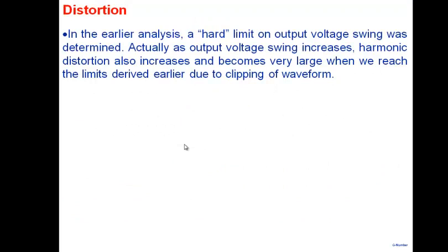Yes. Sir, all these simulations show that it usually fails at the upper limit. That is, the transistor is reaching cutoff way before then. No, that is because of the way I bias it. If I had biased it differently, it would have gone into triode region. It all depends on my biasing. It depends on which limit comes first. Okay, so it depends on that. All right.